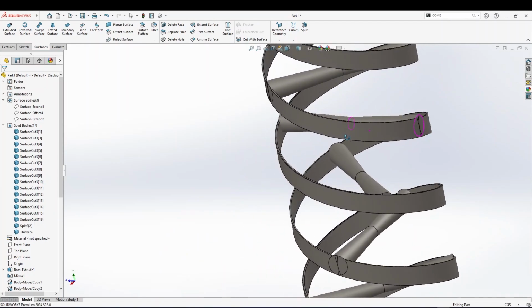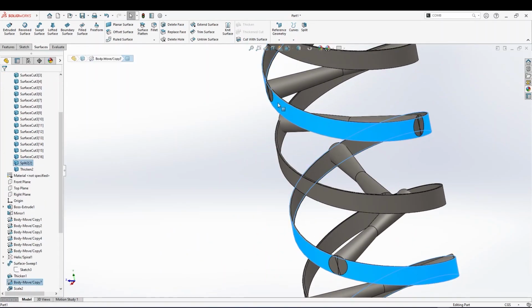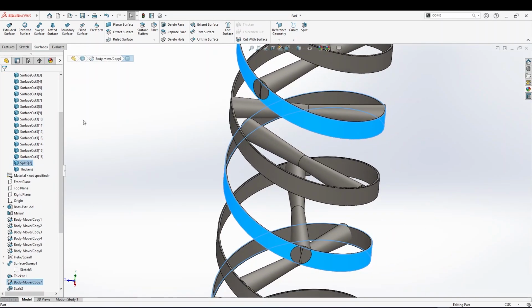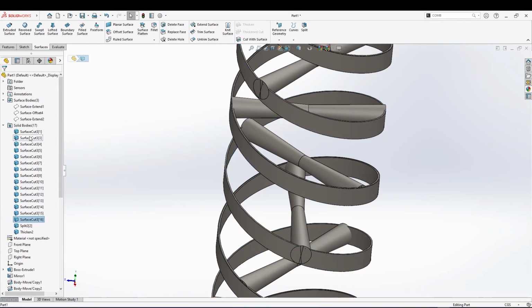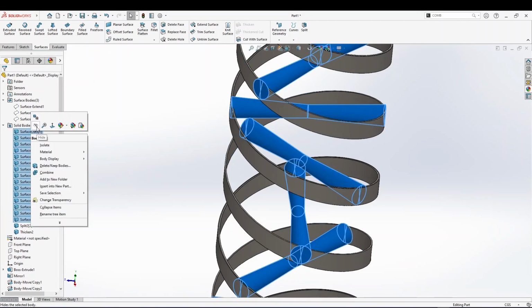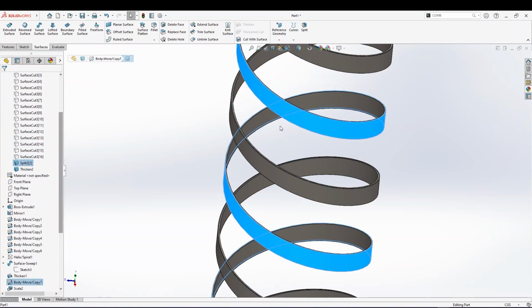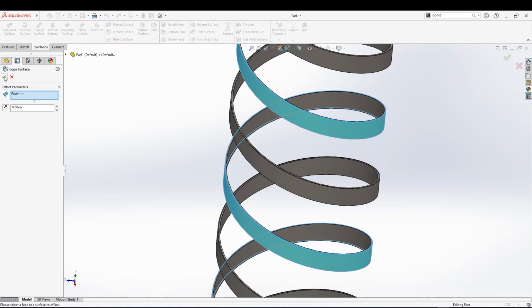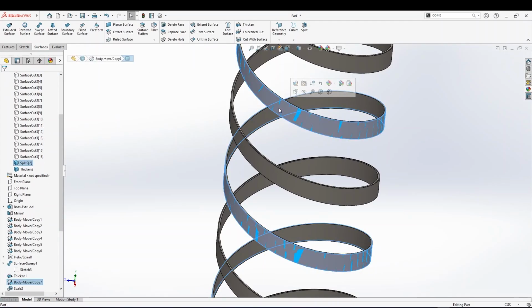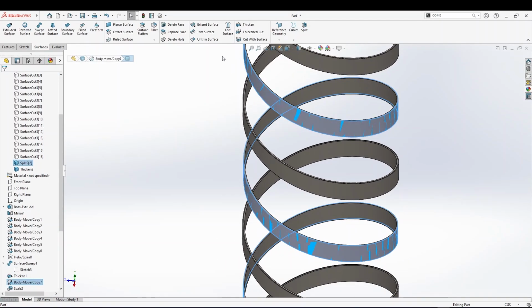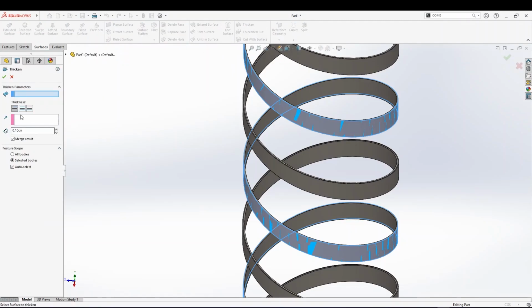Let's do the same thing here. We want to select clearly this face. Again, we press one, hide all of them, just the first one and the last one with Shift, don't forget to hold it. This one, and again, we turn this face into a surface. And how do we do it? Surfaces, and offset surface with 0 distance. Now there is a surface exactly repeating this face, and again we thicken a very small distance,